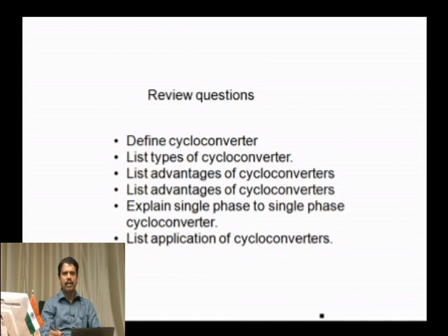So, step down converters are advantageous, with less complicated circuitry. Also we go for high power applications, low frequency high power applications. We can use them for any load power factor. Again, we get a pure sinusoidal waveform. These are some of the advantages we have seen.